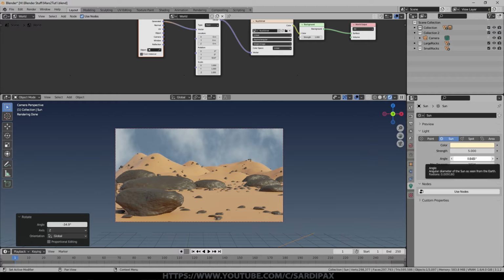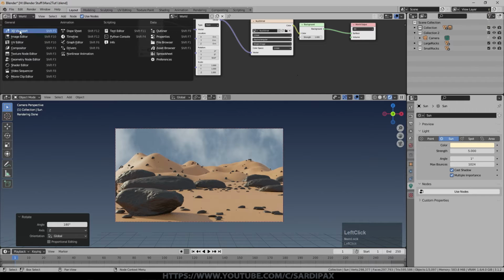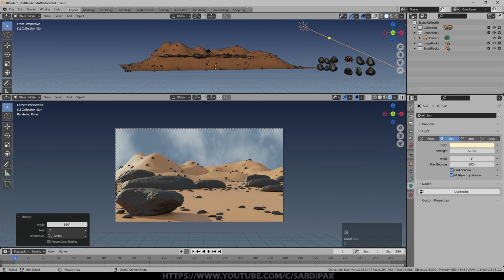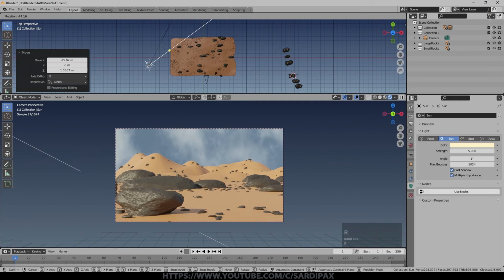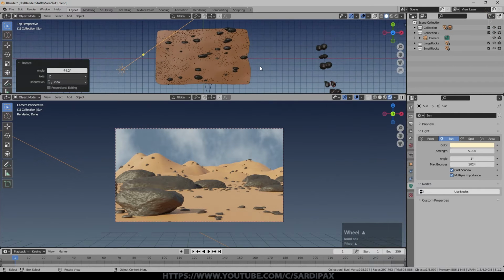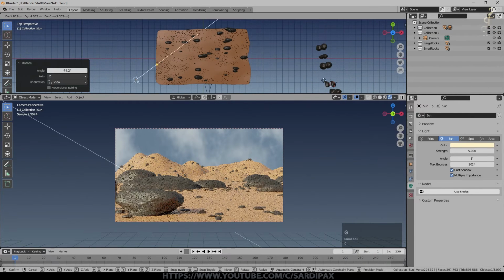Now the angle in theory should be very small, but because I'm representing dust in the air, that actually may increase the angle. I ended up with 1 degree, which softens the shadows and things like that. If I show you what I'm doing over here, I'm just going to move it over to here because of what I'm trying to do with the sun. There, now the sun is slightly behind the camera effectively, even though the object appears to be in front of the camera.